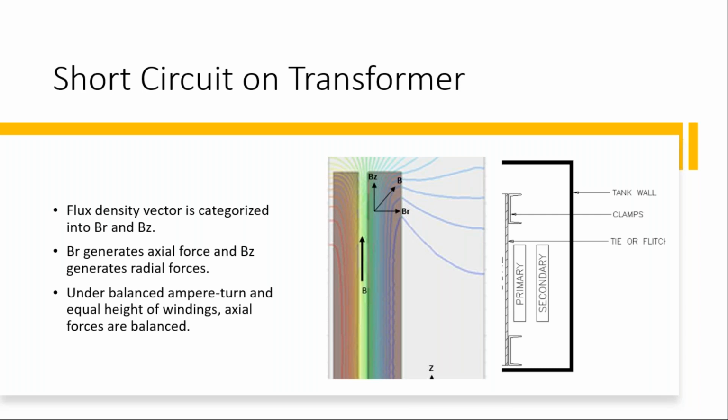When this happens, a leakage flux is set up, and the leakage flux will be axial in the middle of the winding height, and it will be bending at the ends. This can normally be divided into two components, X and Y, or R and Z components, which we use for our winding considerations, to select our conductor size and conductor thickness.